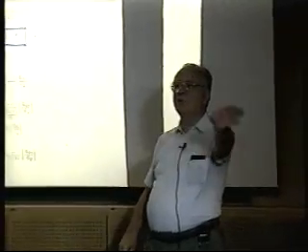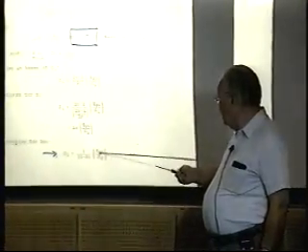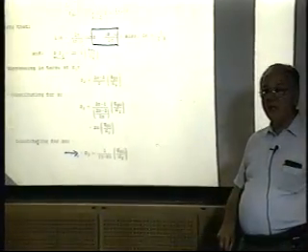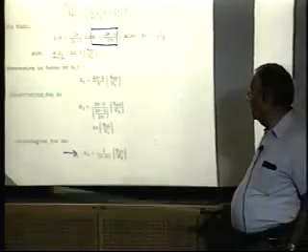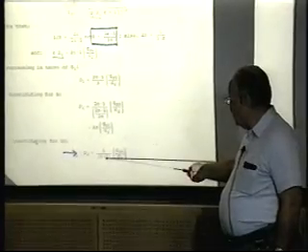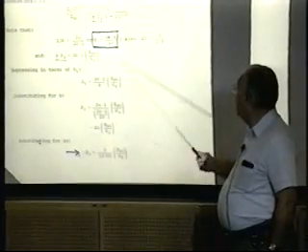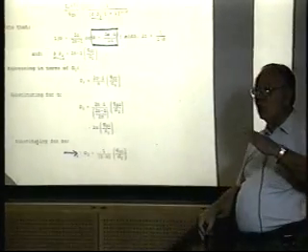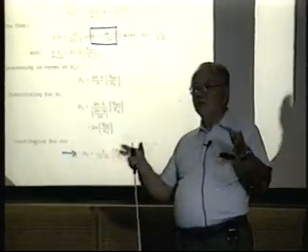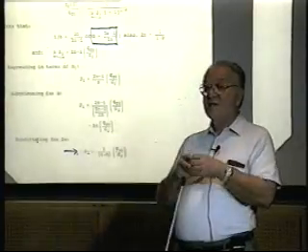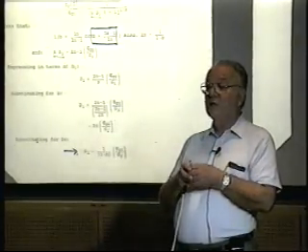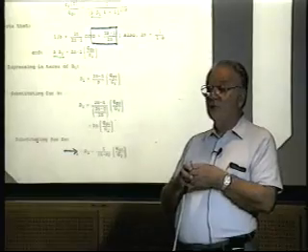At T equals 0 I have no performance data at all. There's my gas in place that I can get from geology. I can calculate a QGI from my KH and skin from a buildup. I can get the B value from the slope of the back pressure curve by including in a reservoir non-Darcy flow and including the size of the tubing at the surface to get a wellhead deliverability curve, and that's the slope I would use.